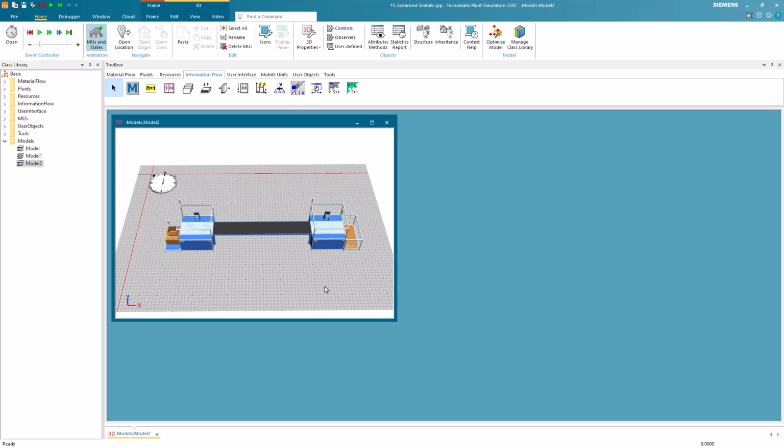However, in a control, we can make more specific adjustments. We could, for instance, distinguish between different MU, and based on the type of the MU, we could program that only one MU should be placed on the conveyor for a specific type. This can't be achieved by setting the capacity of the conveyor to 1. However, to keep the example simple, we will not use different types of MU.